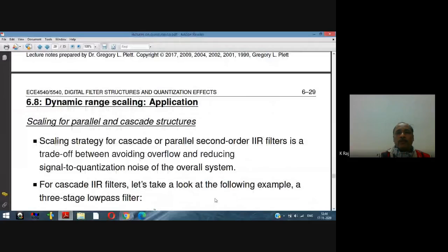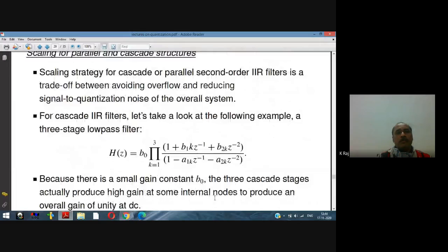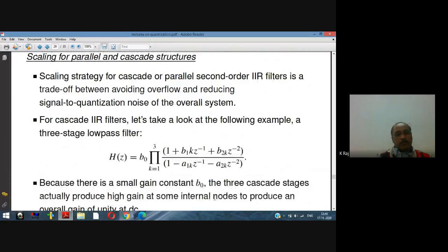In the dynamic range, as we have discussed, the dynamic range of the floating point number system is larger. This is the advantage of the floating point number system, but the disadvantage is that during implementation it becomes more and more complex, and the designing is harder than that of the fixed point number system.